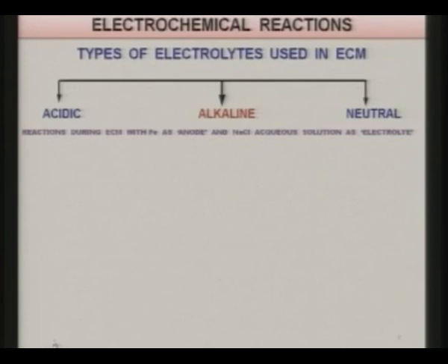that is the normal salt which we eat every day, its aqueous solution is used as the electrolyte. You will find that electrolysis of water, that is the solvent of the sodium chloride salt, takes place, and you get hydrogen gas at the cathode and hydroxyl ions, 2OH with 2 negative charge, formed. Iron is dissolved from the anode, that is the workpiece, and you get iron ions with 2 charges on each one.